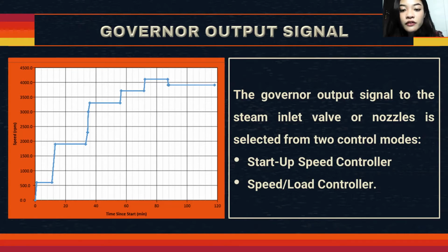In virtually all steam turbine systems, there are operating speeds known as critical speeds. Critical speeds are operating regions where the rotational frequency is near the critical frequency, and high vibration occurs.